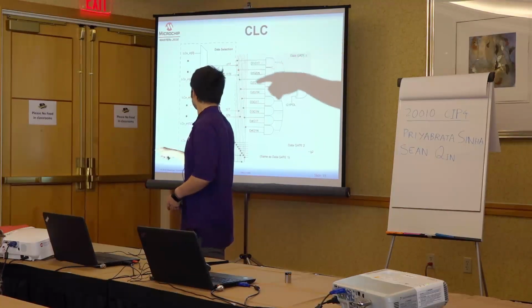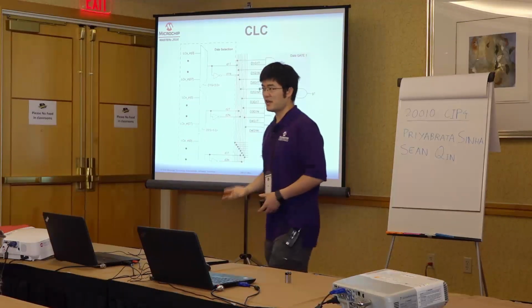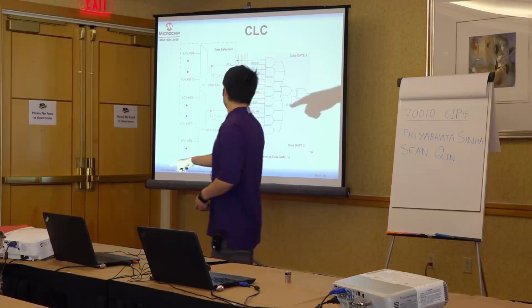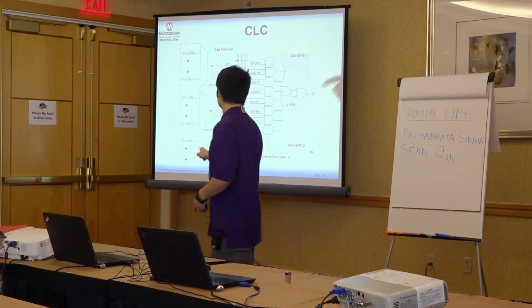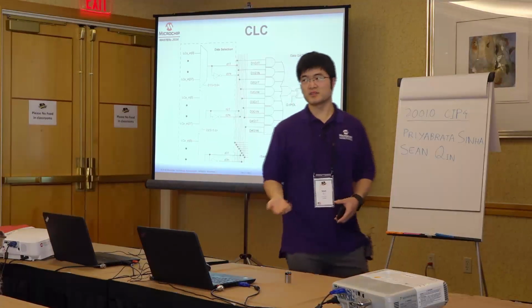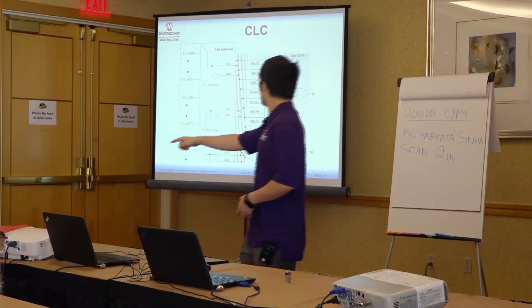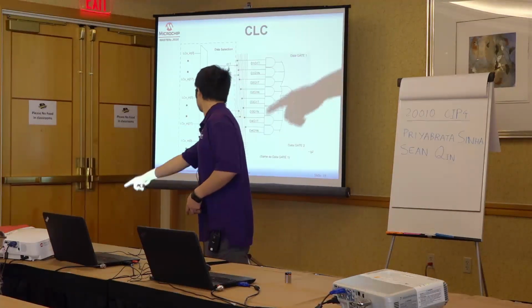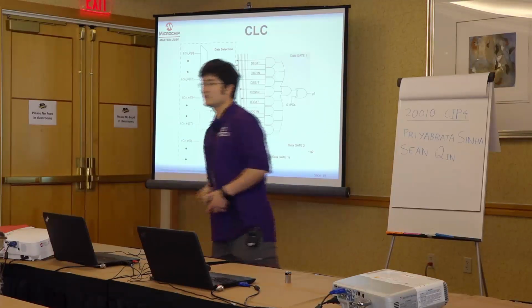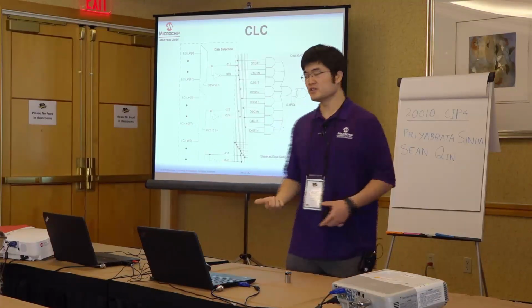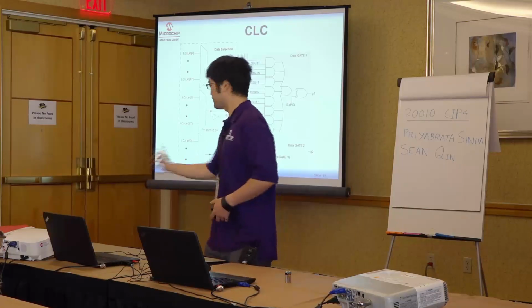Choose your signal, write the bits in the register, and figure out which signals you are using and combining. This is going to generate something called G1. We call it the input candidate signal for the second stage. For each CLC, we have 4 blocks of this output for the next stage, so we have G1 through G4.